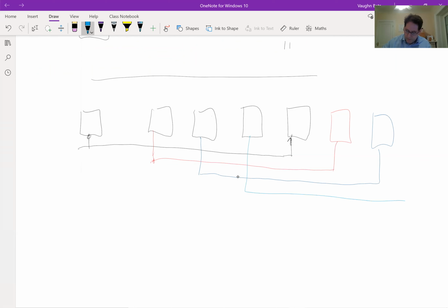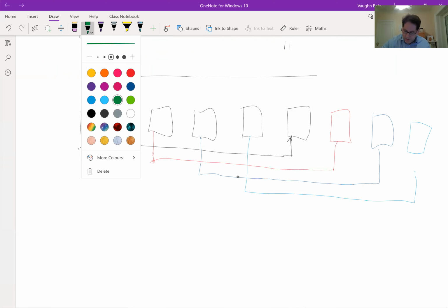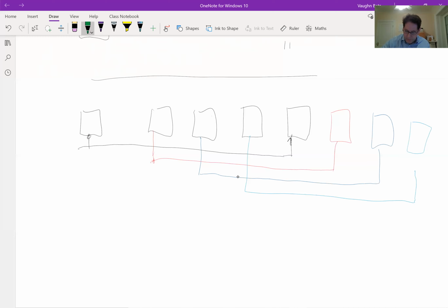Okay, this one also drives away to something that's 4 units away. And now this block, so far I've just done its input. Now I do its output. Its output also goes 4 units away, but it doesn't overlap the first route. Basically the first route is ended, so I can reuse that track, that part of the channel, now for this new one.